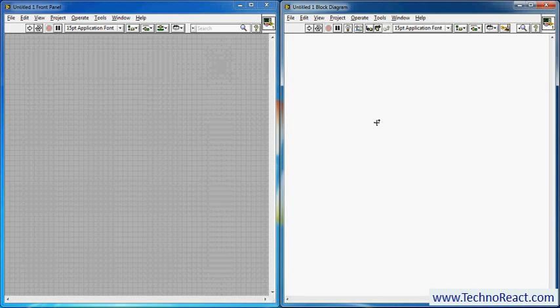Suppose we have two numbers and we want to perform the addition of the two numbers. Then in the front panel window we can select the two numbers and get the output, while the basic operation block, that is the addition block, can be added through wires with input and output in the block diagram window. It will be more clear if I give a demo of how we take inputs and perform the operation. So to start with, I select the basic addition operation.